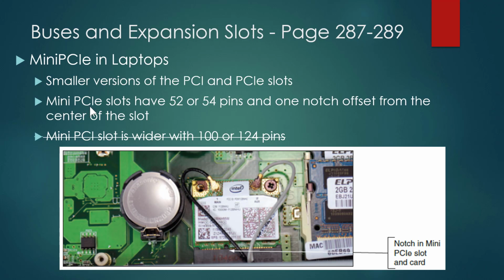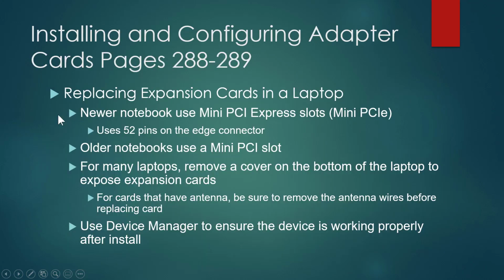I don't think you're going to see Mini PCI anymore. We're now to Mini PCI Express for a long enough time that this would be an extremely old laptop, and you would want to dissuade the owner from replacing this Wi-Fi card, because I'm not even sure you'd be able to get a better Wi-Fi card for the Mini PCI slot. And the computer may not have the CPU power to deal with the newer encryption technologies of the newer Wi-Fi standards. So it may be for naught anyway. So I'm not worried about Mini PCI. Mini PCI Express is kind of your cutoff.